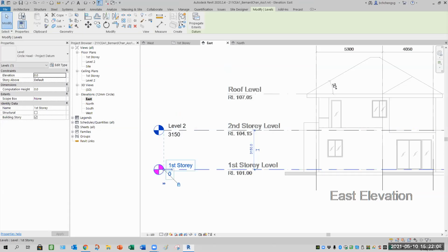Questions? How you actually rename it? Just point at the level, double click. Yeah, you see, you highlighted, right? Look at it, double click. If you want to click slowly also can, see, select outside. You click one time and one more time, it's the same, but double click is faster. See now. So rename.